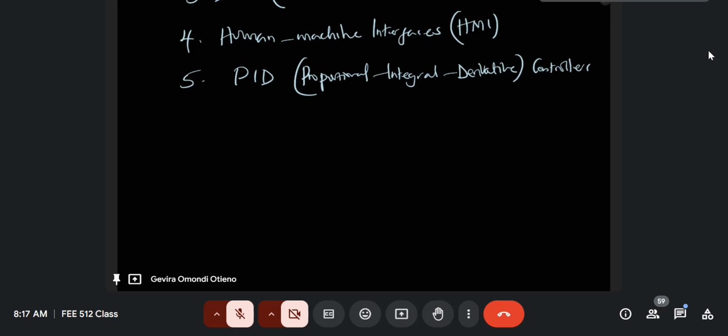These are usually used in industrial automation systems for continuously modulated control of crucial processes. So if you want to control the flow of a liquid somewhere, the pressure of some gas, the speed of a car, or the temperature of a room, you need a PID controller, because it will be comparing the actual output to the target output or the set point, and it will always be trying to keep them as close together using feedback control, a feedback sensor.